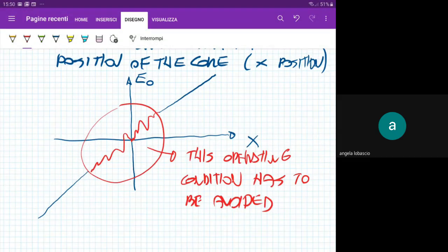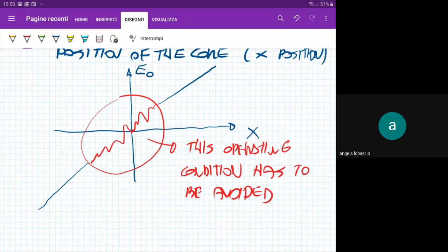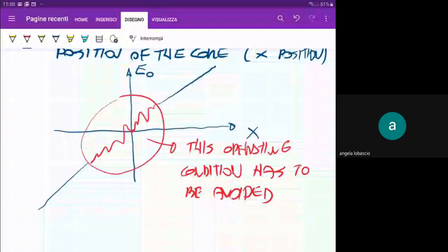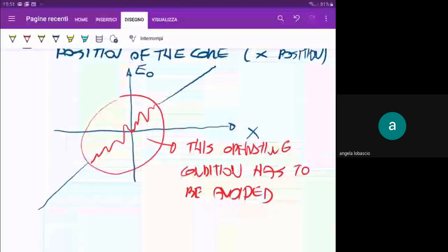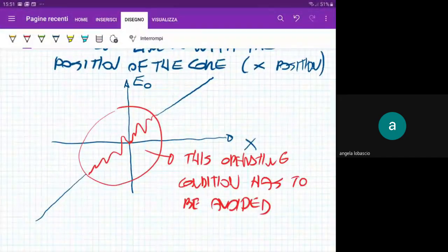Displacement, the x. If you look at that graph, you have the output tension E0, to which corresponds the unknown displacement x. The position is giving you your x. As you saw before with the potentiometer, there is a mechanical link between the iron core and the actual position, whatever the origin of this motion.